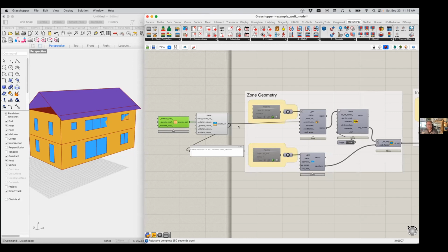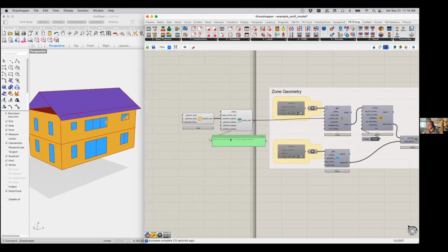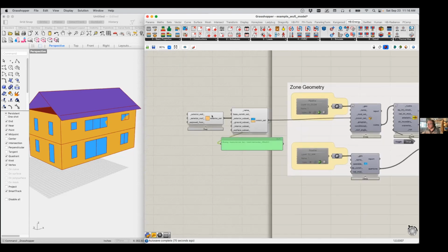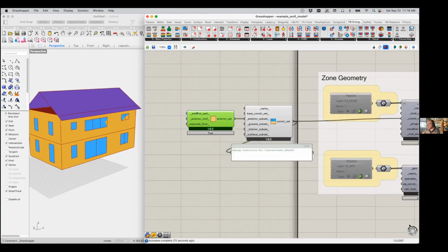So here we're going to override that. We're going to say, no, we're not making some shitty glass office building. We're making a passive house building. And so we're going to give it actual good R values for our walls here. But we haven't yet. All we've done is set up the infrastructure. Now I need to actually build this exterior wall. And we can do that in lots of different ways.